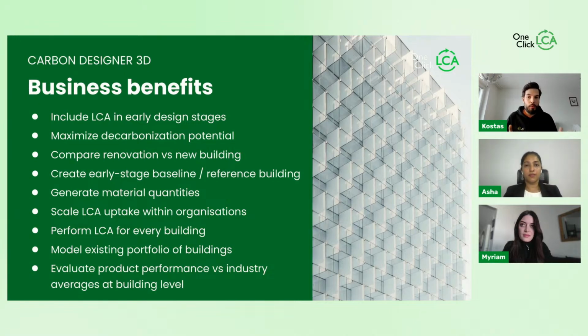And then if we move to the next part, okay, the carbon impact is one thing, but then the tool can create for you a quite representative bill of materials that you can use in the early design stages for all kinds of purposes, like an early cost estimation. Or you can use these material quantities to just fill in the gaps. For example, if you have a BIM model that is lacking some building parts, or if you have an energy model that has only the building envelope, Carbon Designer can help you fill in these gaps.